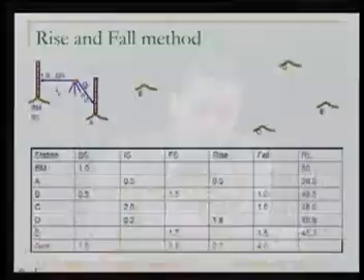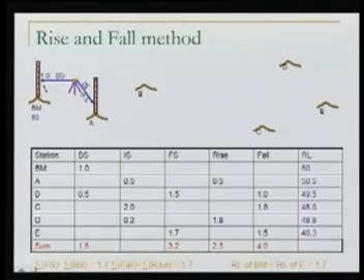We have taken a backsight at the benchmark and now an intermediate sight at point A. By establishing this horizontal plane and using these two readings, we can say whether point A is higher or lower than the benchmark, and also how much higher or lower. Here the benchmark reading was 1.0 and the intermediate sight is 0.5, so you can guess that point A is higher than the benchmark by half a meter. So this is a case like this.